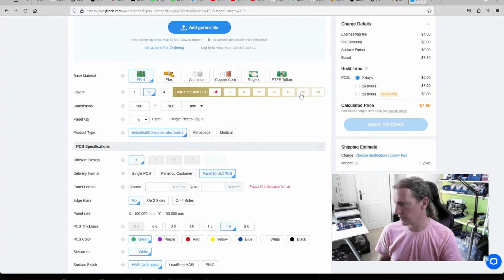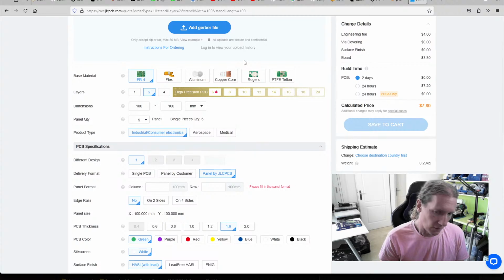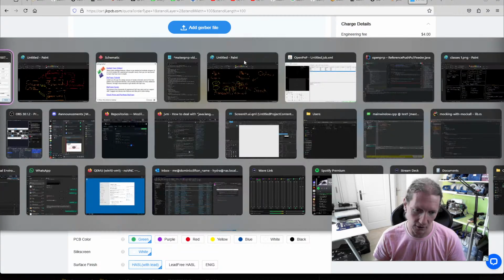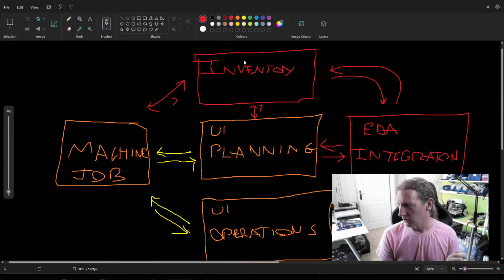You just say leave a 3mm gap between them, put the mouse bites on the corner PCBs here, put the fiducials in the corners, and put the label on top. It's fairly common stuff. But how does that impact our workflow? So now you've asked the fab to do the panel. So you don't have any machine files yourself with the fiducials on it or anything like that.